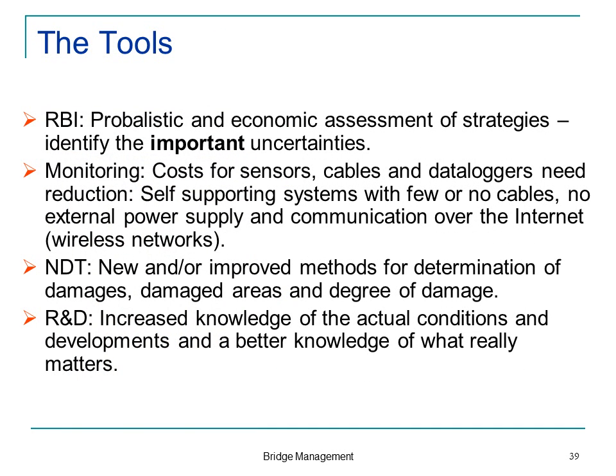Yeah, tools for doing this. One, of course, the risk-based inspections, the monitoring, the NDT. NDT stands for non-destructive testing. Well, it can be a little destructive, but it means essentially you can come back and measure on the same thing. If you're taking a concrete core and you're testing its compressive strength, then that is destructive testing. You cannot test the core again.